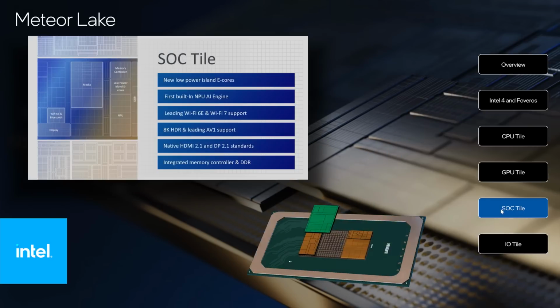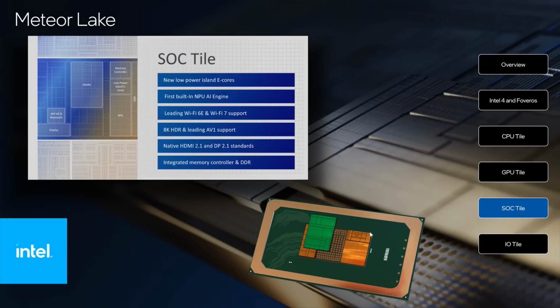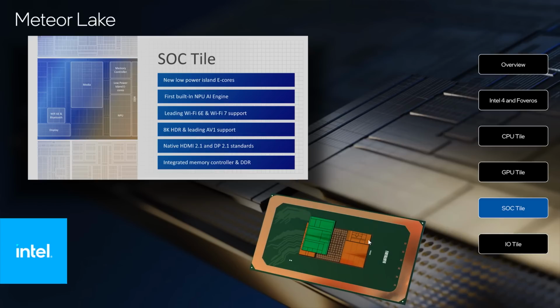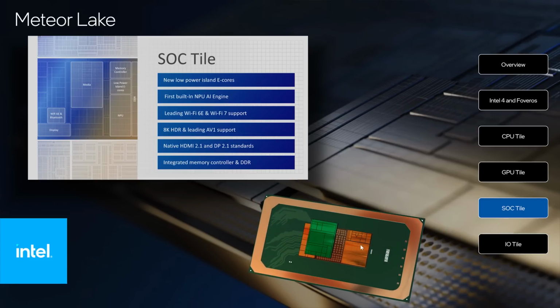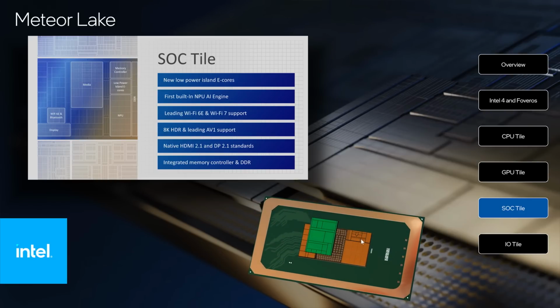In Meteor Lake, we have our SoC tile, right? That's new. So there are SoC tile specific algorithms that are part of our enhanced power management that got incorporated into Thread Director to reflect to the OS that now is the time to keep the work on the SoC tile, or now is the time to move the work from the SoC tile, right? So, just to give an example on that, right?